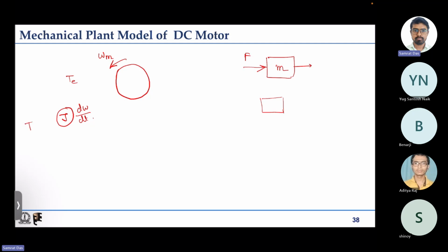The torque that we need to apply to change the speed at a certain rate has the proportionality constant J, the polar moment of inertia. So if we have a rotating motor, then it will certainly have a polar moment of inertia. That means if we want to accelerate or decelerate it, our applied torque needs to provide that component of torque.